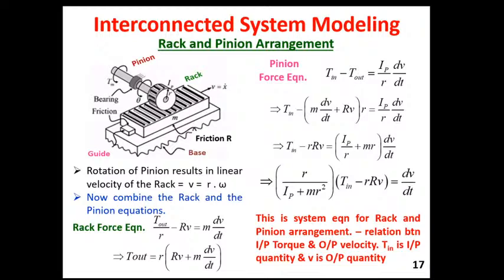But if the system has some initial condition, there will be some kind of frictional dynamics or random dynamics in the system's initial response. After that dynamics or transient is over, the system will start getting settled. So the initial condition actually prolongs the settling time. The greater the initial condition, the more time the system needs to settle.